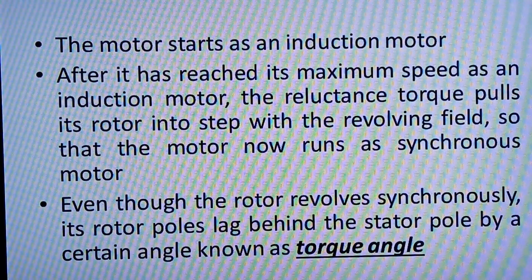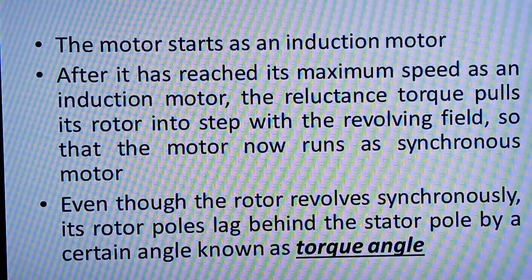Here the rotor has no windings, so at the initial condition this synchronous reluctance motor starts as a normal induction motor by induction principle. After the motor reaches around its rated speed, more than 90%, or 85 percent, then the same synchronous reluctance motor can act as a normal synchronous motor. So this is a combined characteristic of synchronous reluctance motor and induction motor.